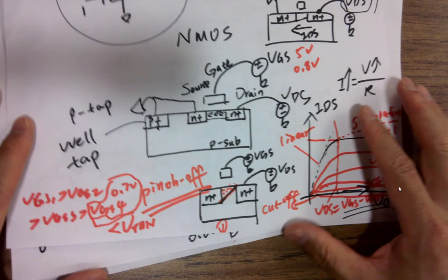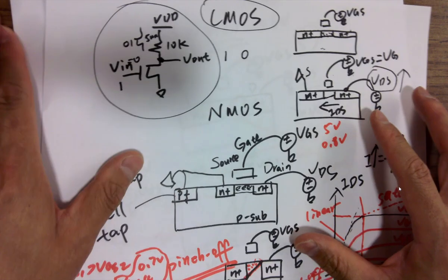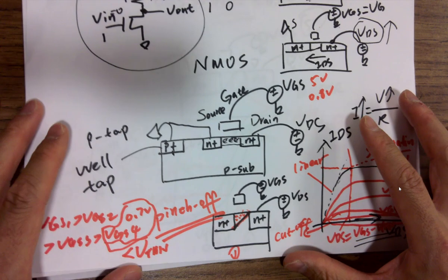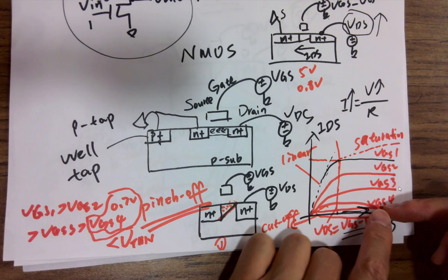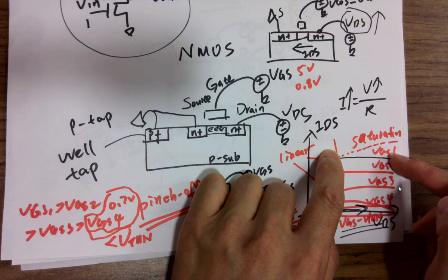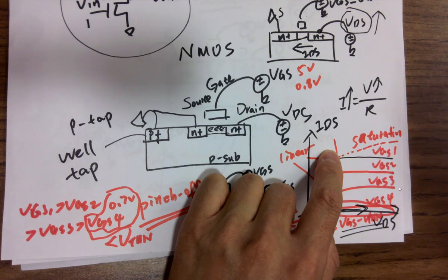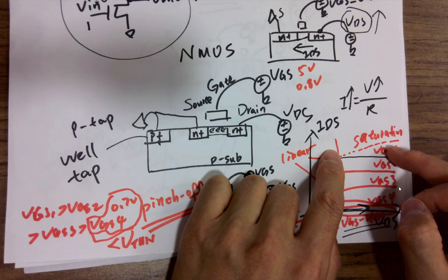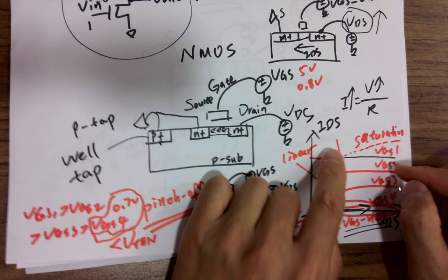So that's why a lot of people are using transistors as a model of a voltage-controlled current source. Why? Because as you increase the voltage, you are increasing the current source output current. Right? Questions?